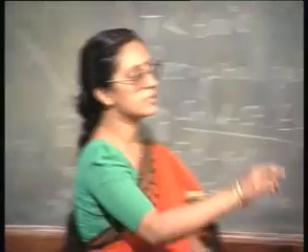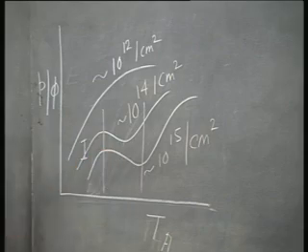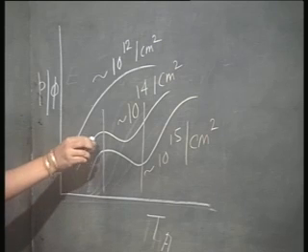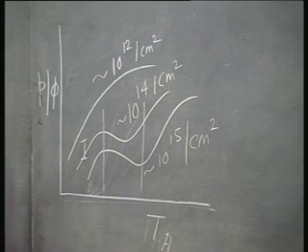And in this region 2, in this race, boron is losing, silicon is winning. So, silicon is kicking the boron out from its substitutional sites and itself going and sitting in those places.